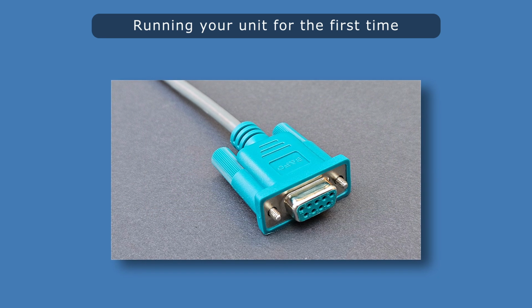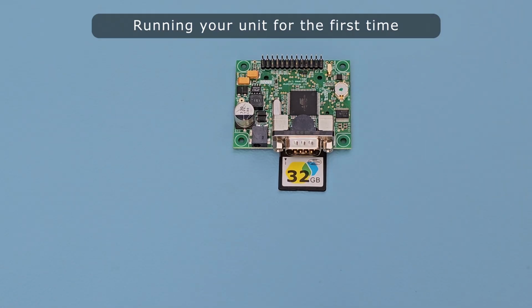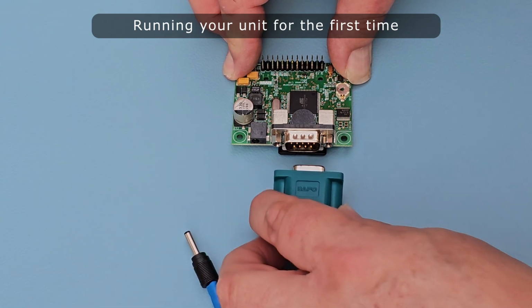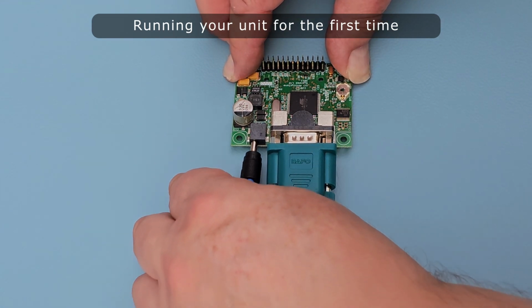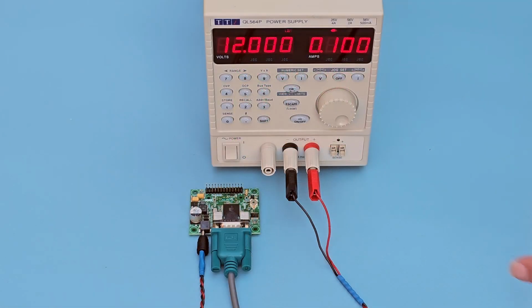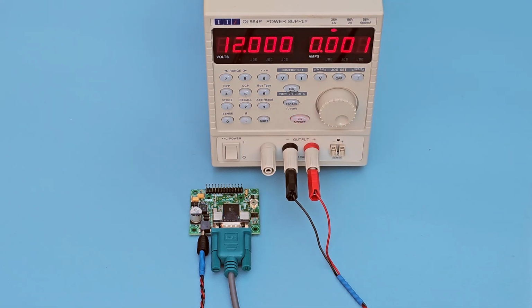So if these settings are compatible with your application, then all you need to do is check if there is a media card inserted into your unit, and then connect your RS232 data source. Connect a power lead and apply power in the range 9.5 to 18 volts. Your unit is now recording data. Turn the power off to stop data recording. Repeat as required to append more data to the store.